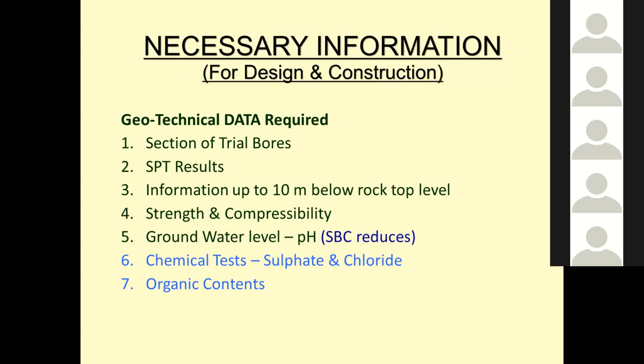And what you will be requiring as a design engineer: section of trial bores, SPT result, information up to 10 meters below rock tip level or rock top level, strength and compressibility, groundwater table,